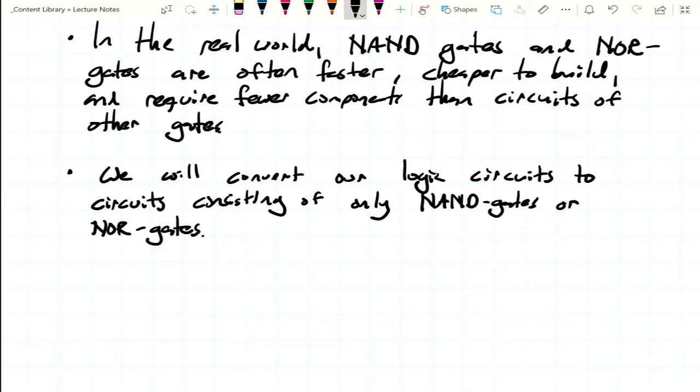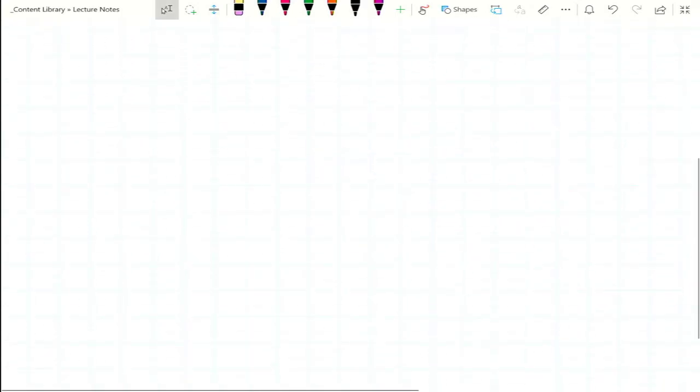So we've got our process. We're continuing to develop it. We started with truth tables or minterm, maxterm expansions, and now we have Boolean expressions. We optimize those using K-maps. We design our circuits in a standard form, like AND/OR, OR/AND, or multi-level versions of that. And then the next step is to convert them to circuits of either NAND gates or NOR gates, because if you do that, your circuits will be much more cost effective to manufacture. That's kind of the last step, to build everything out of NAND gates before you go to the presses. So let's talk about NAND gates and NOR gates on a basic level real fast.